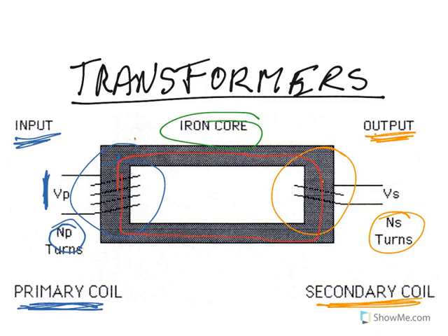And so again, we've got our magnetic field, which is changing, and a changing magnetic field induces a current and a voltage in our secondary. Alright, so with alternating current, you get a field produced in the primary coil which induces a current, voltage or EMF in the secondary coil.